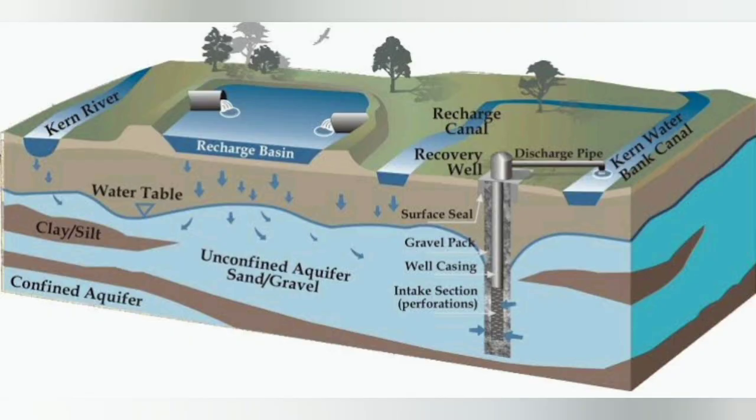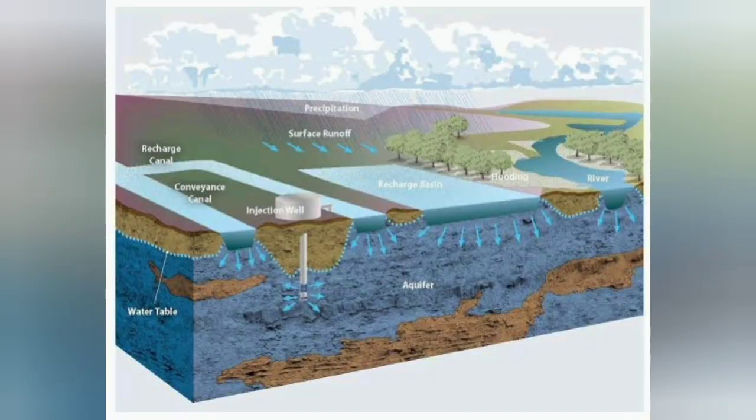Capillary forces continuously divert gravity water into pore space, so that the quantity of gravity water passing successively lower horizons is steadily diminished. This leads to increasing resistance to gravity flow in the subsurface layer and a decreasing rate of infiltration as a storm progresses. The rate of infiltration in the early phases of a storm is less if the capillary pores are filled from a previous storm.